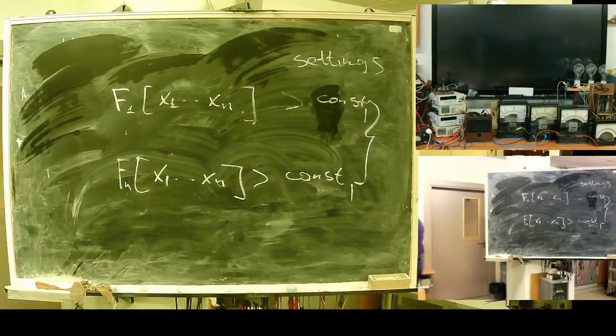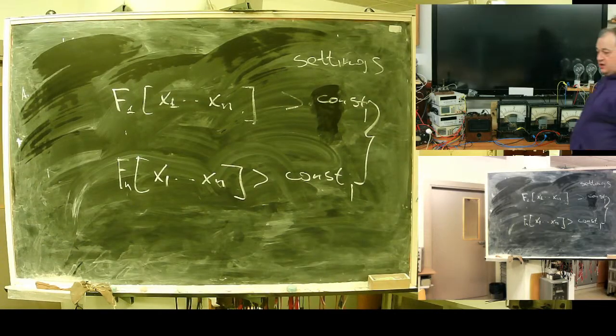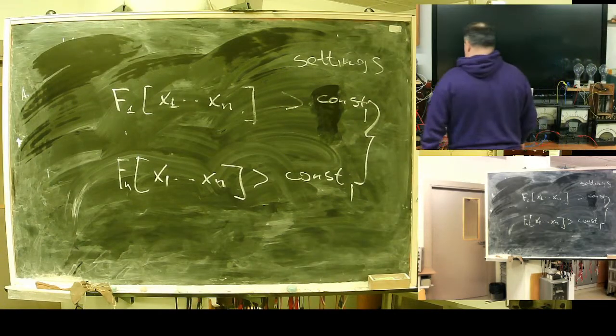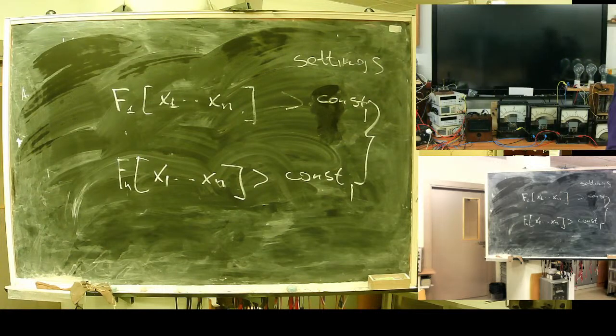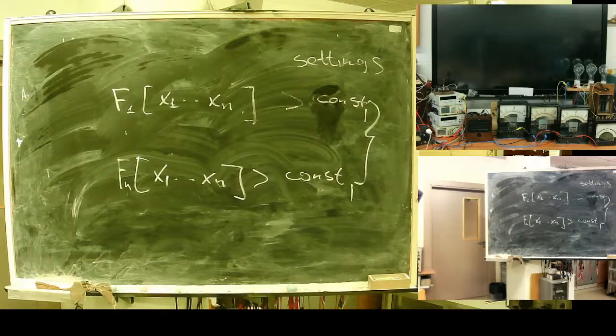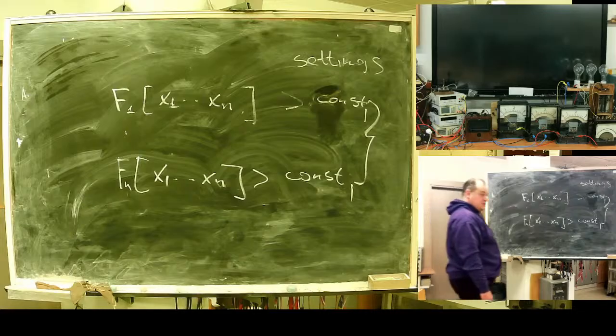So some kind of function calculated on the basis of input signals should be compared to some thresholds. If above, we need to take an action, starting from simply sending a signal that something is wrong, and ending with a global decision to separate the power system into parts.